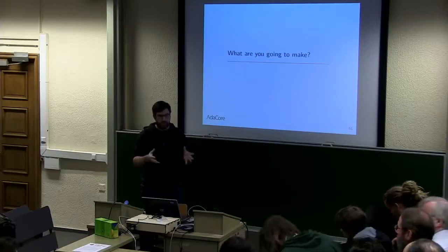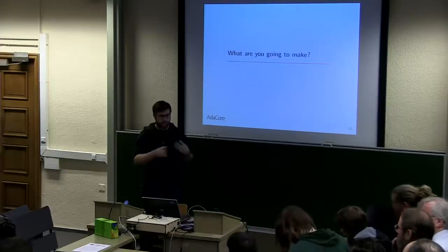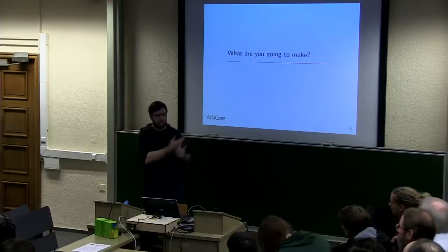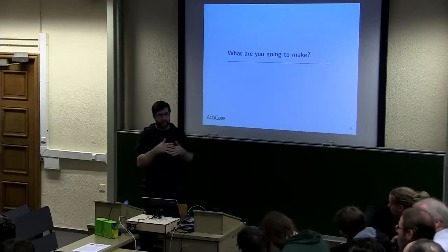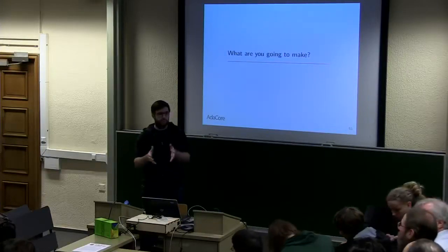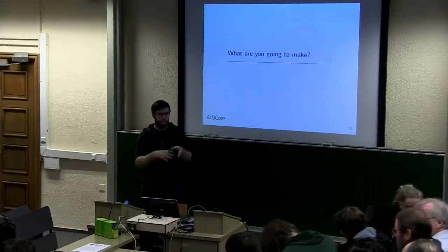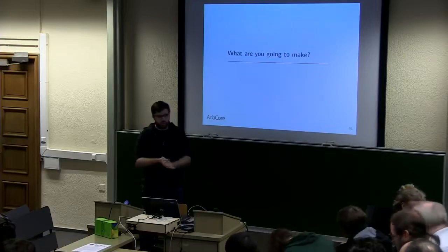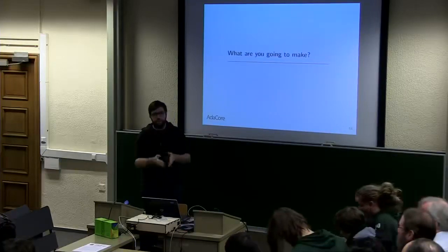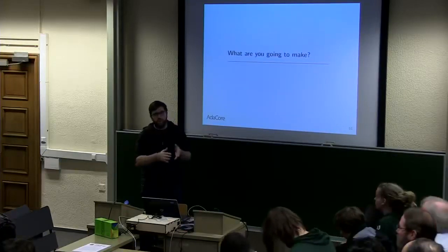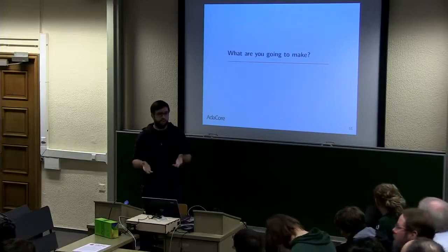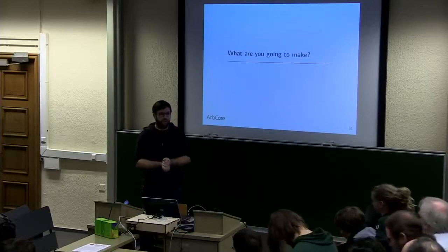What you can do if you want to save energy is, well, first in the kernel, so that implements the task inside the runtime. When there's no task to run, we put the CPU in wait mode, so wait for interrupts. So it's somewhat lower power mode. And the next solution is to really shut down. So if you have a STM32F4, you will have to shut down the CPU to save energy. That's all we have so far.